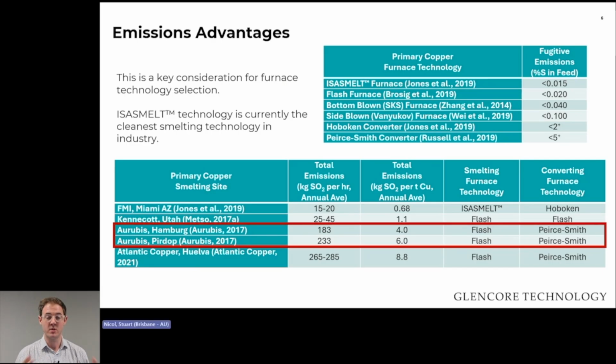If we look at most modern smelters, one of the first and most important decision points that people make has got to do with environmental permitting and emissions. This is one of the first things that people assess. For a certain specific location and jurisdiction, people have to meet the local emissions limits, and there are a variety of ways you can meet them. People achieve this with tertiary, secondary, and more advanced hooding options.